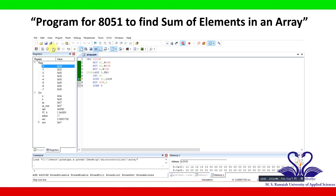Then again DJNZ so that your R0 value is now 34. R0 is incremented and it again comes back to the loop. Finally, for your complete array of elements, the result is obtained in your accumulator. So you can see in the accumulator you are obtaining the value of 5F.